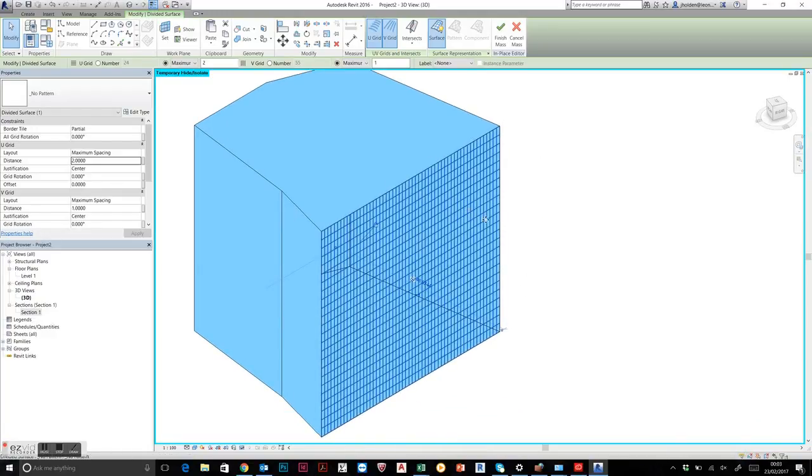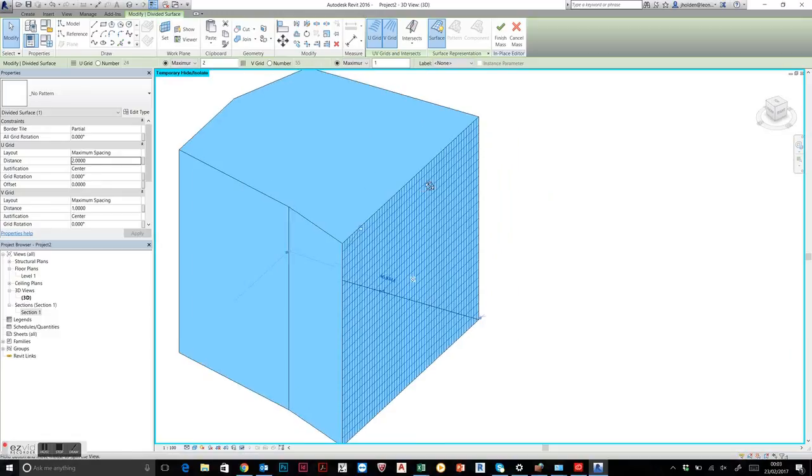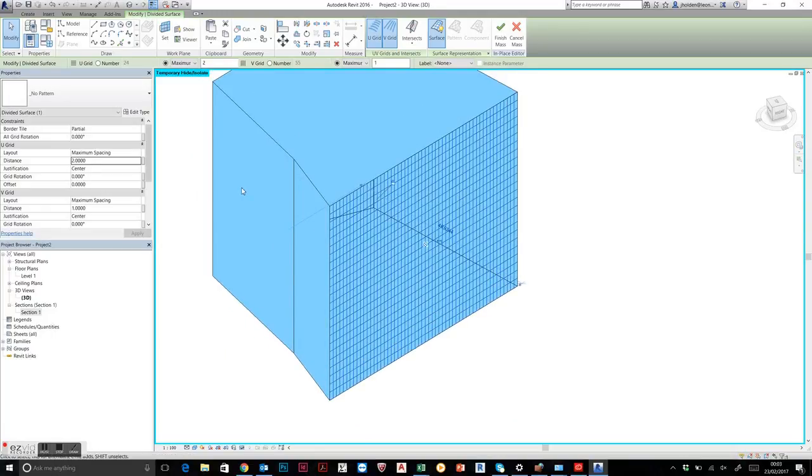If you can, if it's a panel and it's going to be, well, somewhere to 10 meters, make your panel in meters, somewhere between 5 and 10 meters. It just again brings a sense of reality. I mean, I'm not saying Revit can't do it, but the math gets pretty hard and things start breaking, CPUs start burning out.